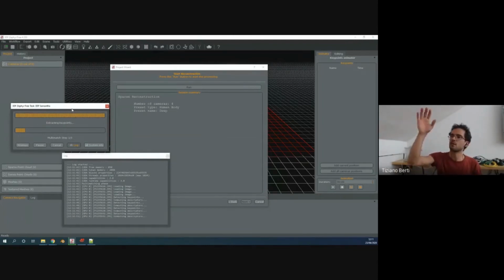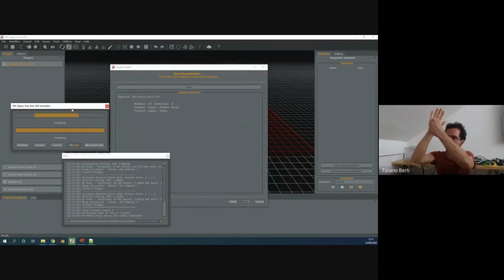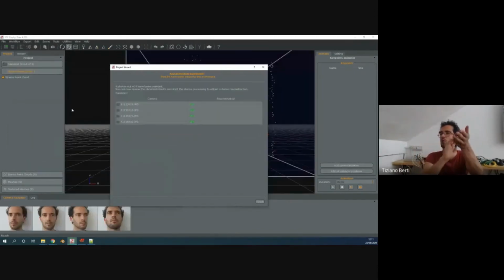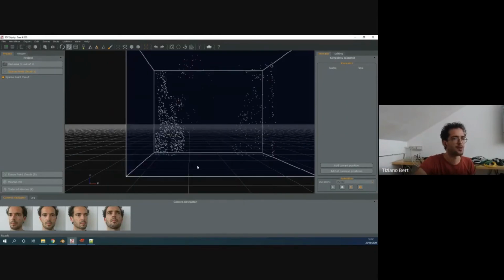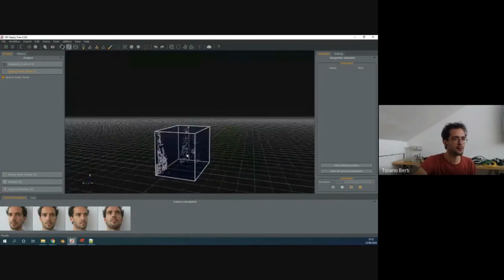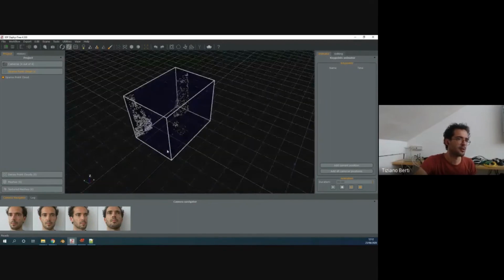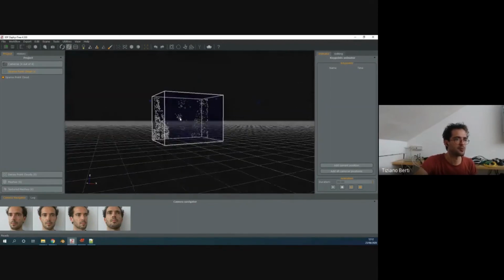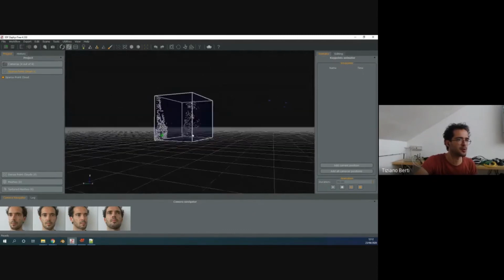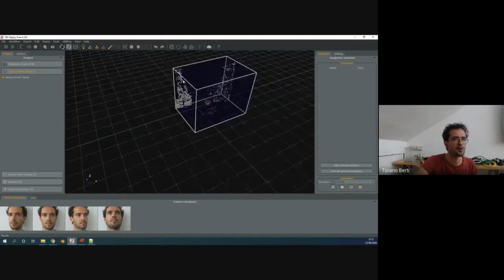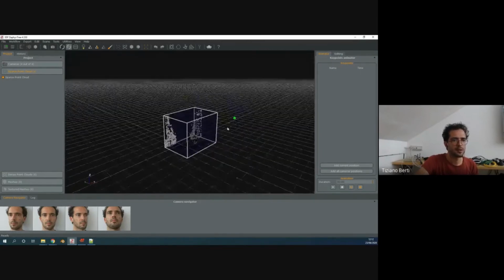With the data set of my hand, the one with all the drawn stuff on top, it was not able to align one side to the other, because there are not many photos from the top. Default was not enough to get the proper alignment of that part, so I had to switch to deep alignment to get it better. As we can see here, we already have some points on my face, which is this part of the point cloud, some points on the wall with the shadow of my face, and here not so visible.